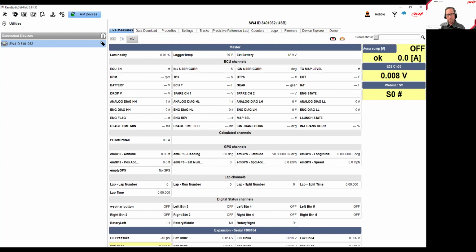Yeah. You can, however, it would be clunky and it would be an every time situation. So if you wanted to activate your fan, you could tie in safe ignition as an activation status. So once the PDM goes live, it's going to change the state of its safe ignition from 0 to 1. And now I can use this as an OR condition.